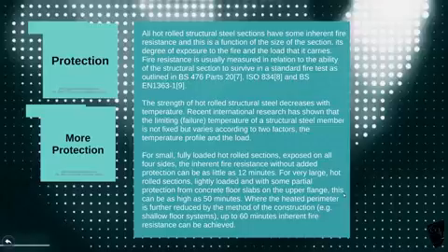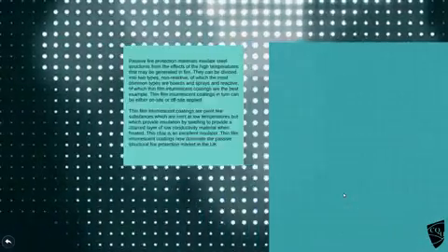If you've got really big sections, which haven't got a lot of load on them, and they might have a little bit of protection from maybe the concrete floor slab, encasing just a little bit of it as it passes through the slab, etc., they might go up to 50 minutes. And when the perimeter is further reduced, you could get 60, but as you can see, it's still not a lot. Now, this might give an indication why we have sprinkler systems to try and put fires out as quick as we can. But there is some protection that we can put onto it.